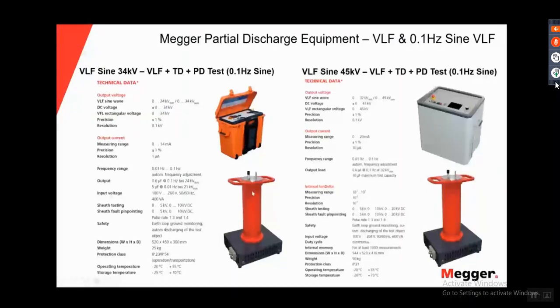And for the PD test, we will use this coupling capacitor, our PDS62. The next unit we have is the VLF Sine 45 kV. This unit also uses a 0.1 Hz sine wave shape. In this case, we can also do the VLF test.